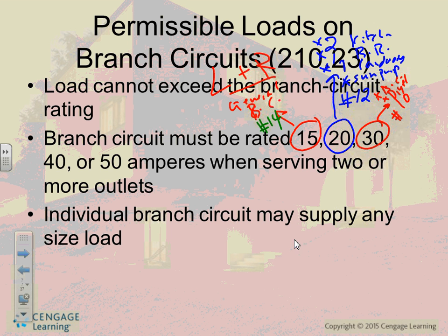I want to add to the wires the voltages. What voltage do we typically use with the 30 amp? 240. This is a 240 circuit. What voltage with these 2 guys? 120. You can see now, when you go higher than 20 amps, almost always you're getting into the 240, 2 hots. Am I making sense in terms of wiring? Okay, so now let's go to the 50 and 40.